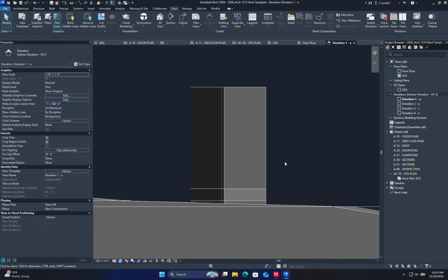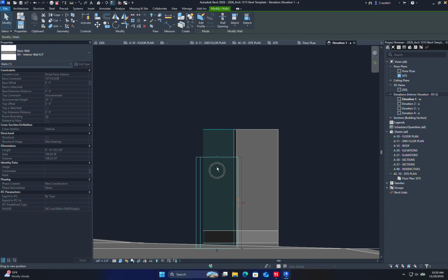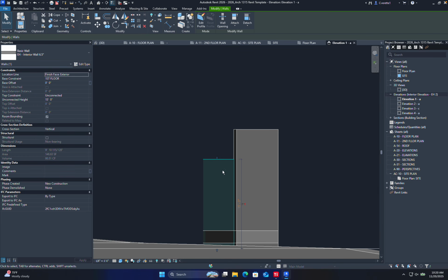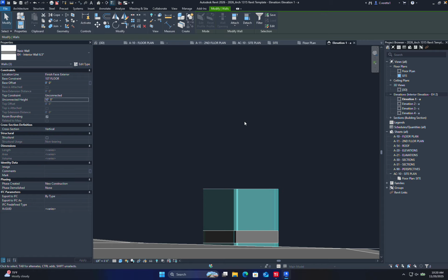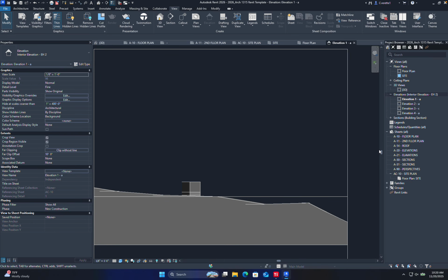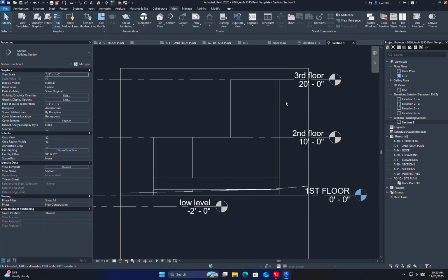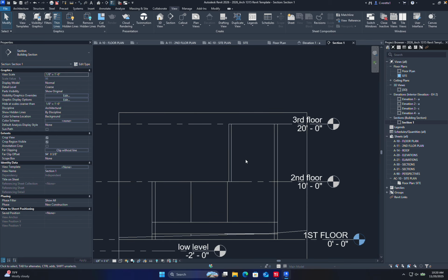There it is. And we'll go to a shaded view, and clearly now you can see that these walls are way too tall. Now, to be fair, we can select all of them, and we can go, well, those are 10 feet walls. We'll click it, and it'll immediately, boop, all the way to 10 feet, right? Which is great, but I may actually want to do that a little bit easier. And in fact, I may need to go to my section, so let's go to sections, double click, and we'll open that section tab. In fact, you'll see that I gave you some floors to automatically do this as well.